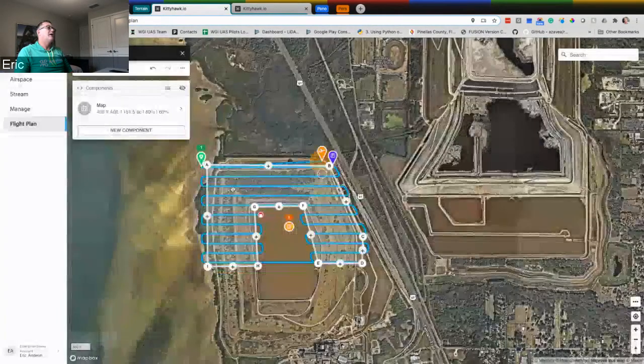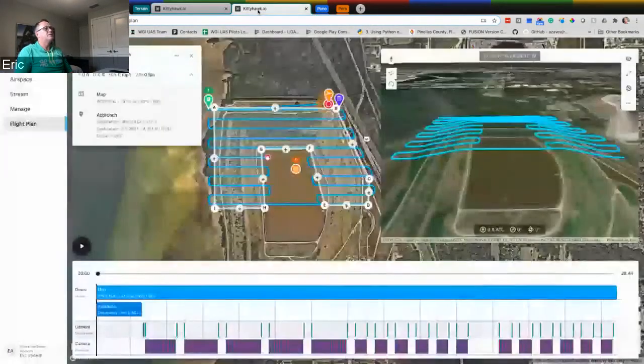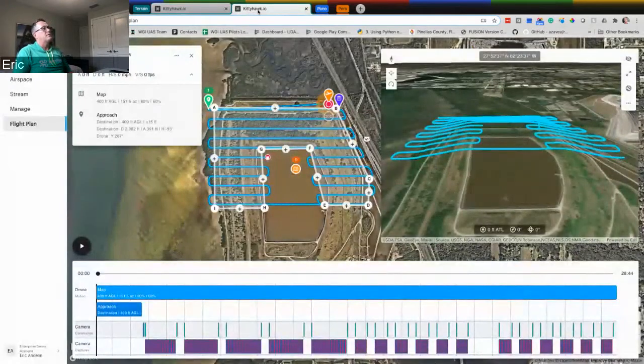I went ahead and put this into the mission preview as well. I did this earlier just for effective time so that we have it here. But what I really want you to see again is we're referencing ground. So it's pulling that local elevation model, and it is now terrain following, not just flying.